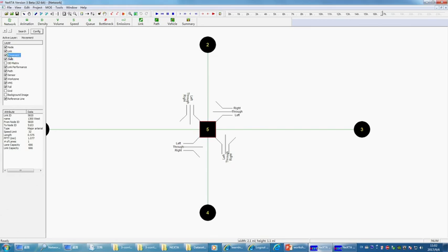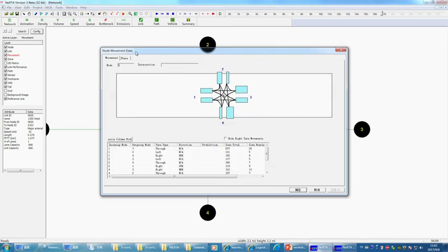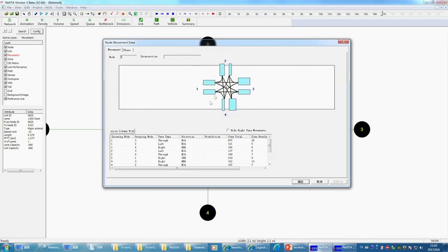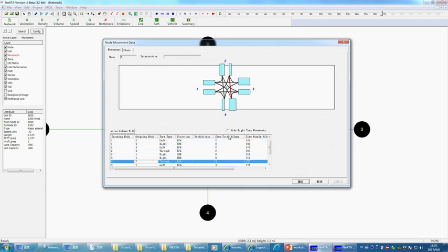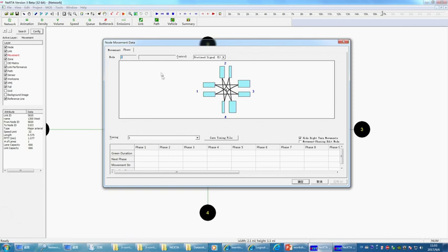So under this movement layer, go to this node, right click. You can visualize the turning movement structure. On this movement layer, you can click on each movement to check the corresponding simulated volume, simulated hourly volume, and the simulated delay in seconds. If you move from the movement page to the phase page, you can generate the corresponding signal timing plans. Okay.